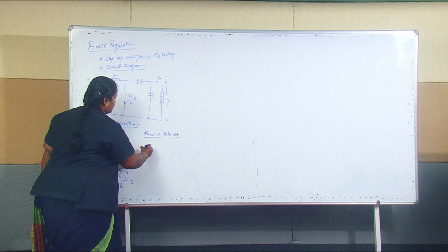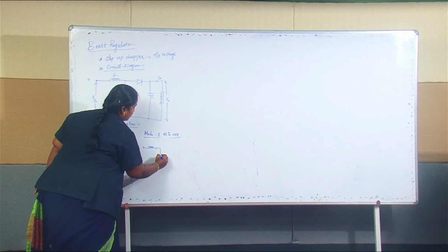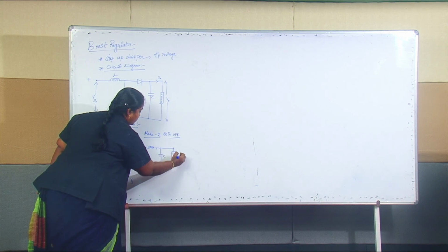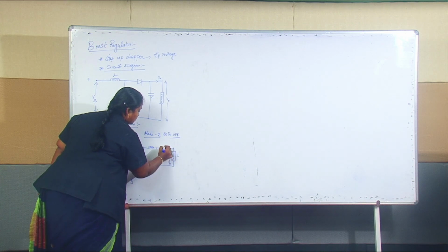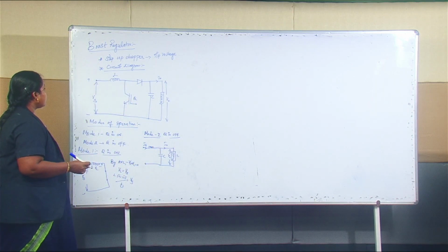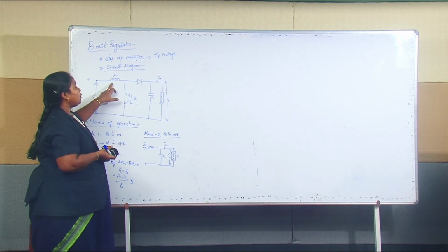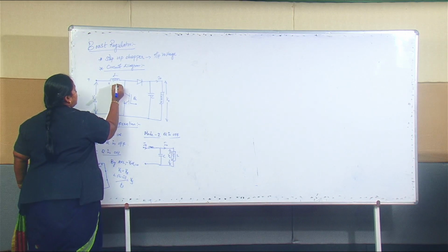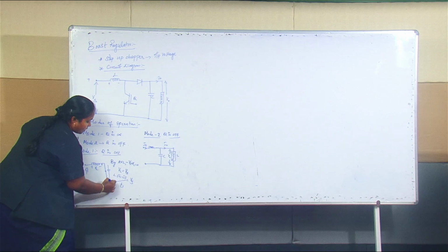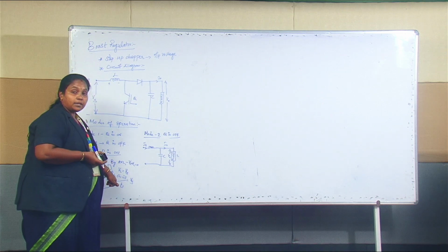So when the switch is in the off state, inductor, we have a load here, capacitor, load L, and let this one be your V naught, I naught, Is. Now if you consider the main circuit, when your inductor is charging, it has a polarity of positive and negative, right? So the transistor is turned on. In that case we have a shorted path, and we have a separate capacitor and load here, right? Your capacitor is charging your load in this case.